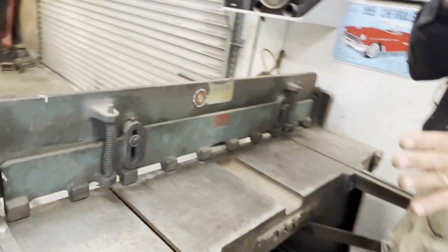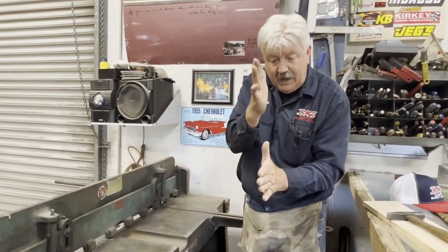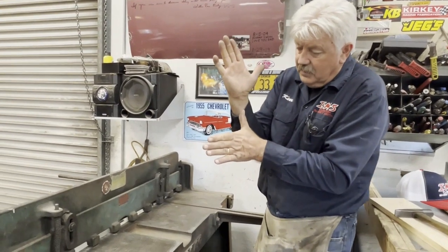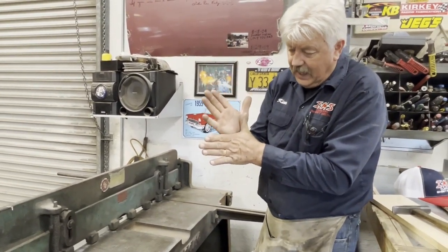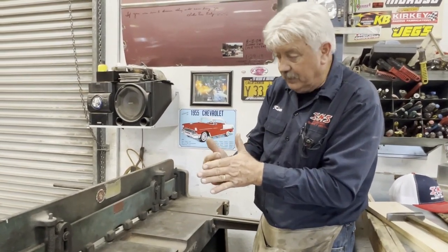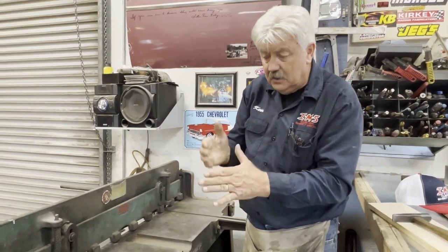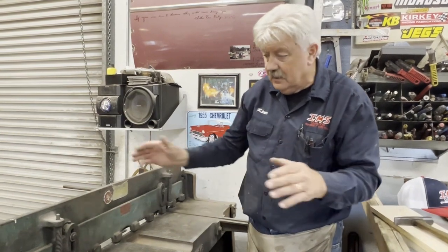And there again, we're going back to on the stomp shear, we have a stationary blade on the bottom and we have the moving blade on the top. And so the blade comes down at an angle. So there's always a focus of energy at the point of shearing, because remember, when we're shearing, we're stretching the metal to its point of failure. We got to stretch it to the point that it gives up and allows us to complete the shear.